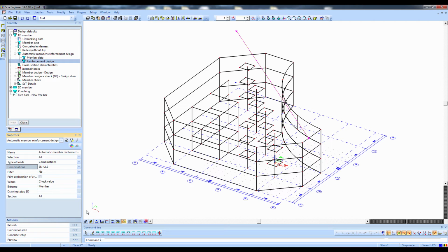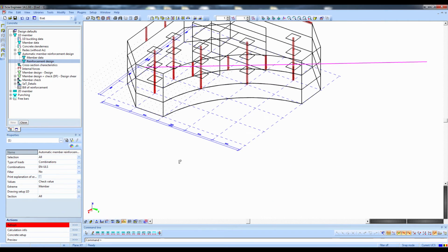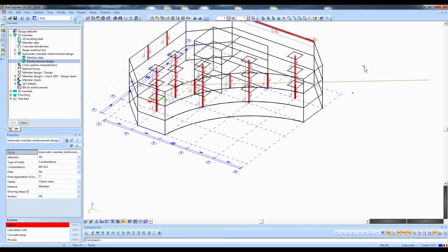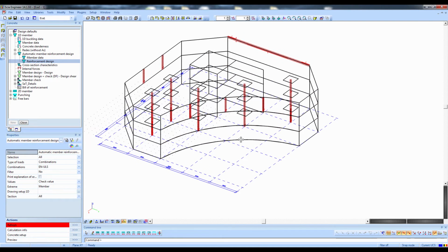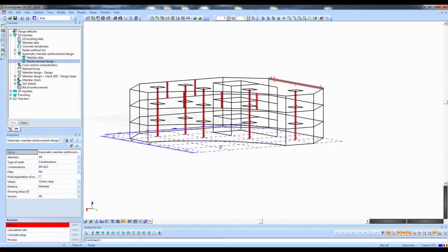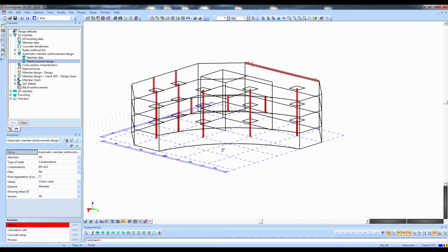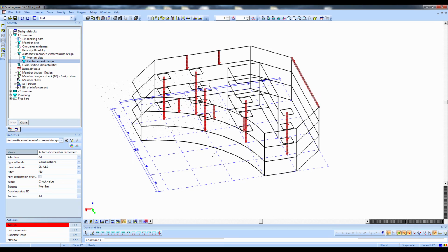I use it on all values, and now it will calculate the theoretical amount of reinforcement which is required for each element. Then it will take a template and use that template to add that reinforcement. The results are that you can see the reinforcement in all elements. So this way it becomes very easy to add reinforcement into elements by just letting the program do it automatically.